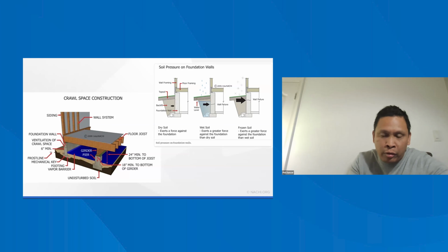It's interesting. When we build, sometimes the builders will install what we call wing walls around the foundation. When we're at a resale, or doing a final inspection or an 11-month inspection before the 1-year warranty expires, we're not going to see if there's a wing wall on that foundation, because it's buried underneath the ground, right? But the builder is doing their best to minimize the amount of pressure going onto the foundation wall by installing these separate walls to help relieve some of that pressure.